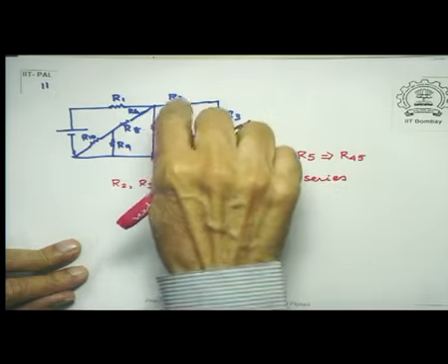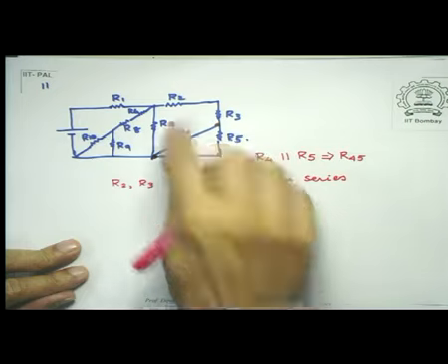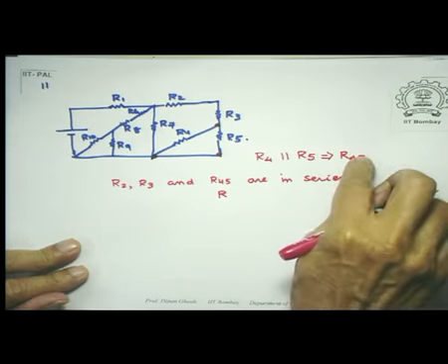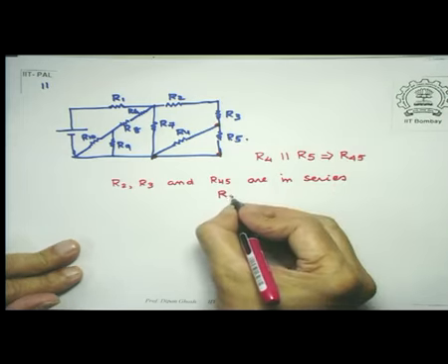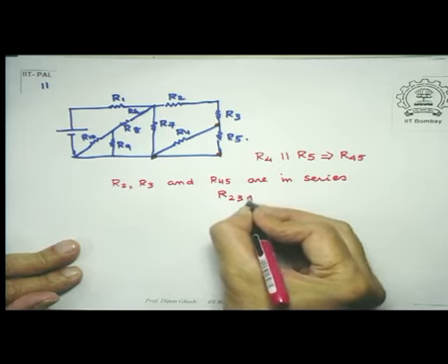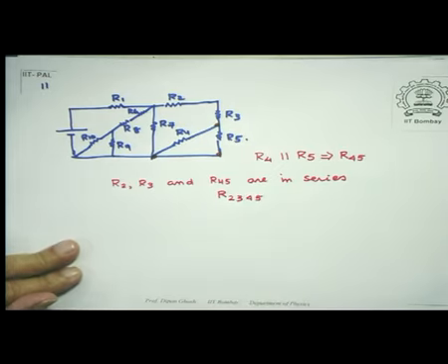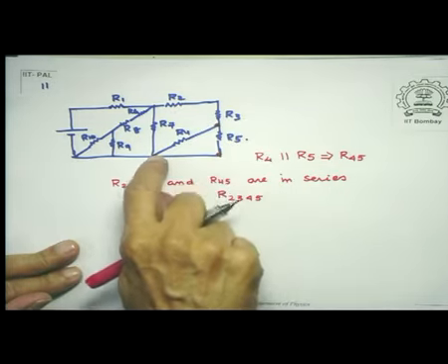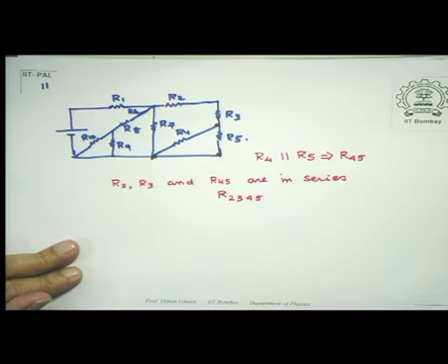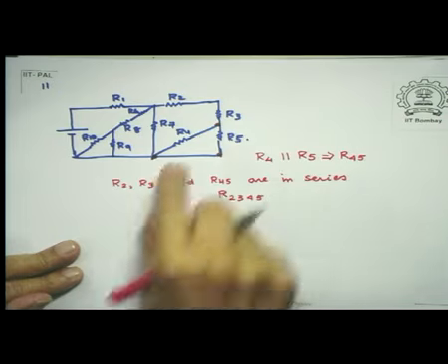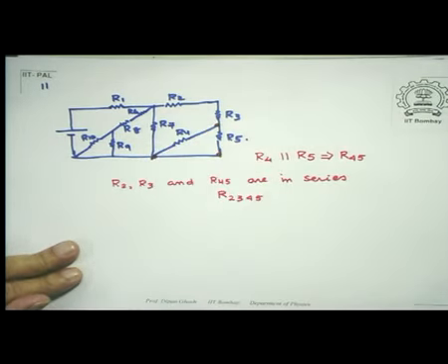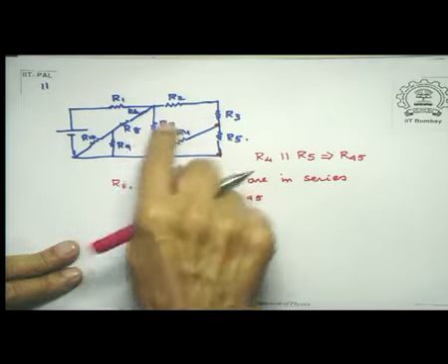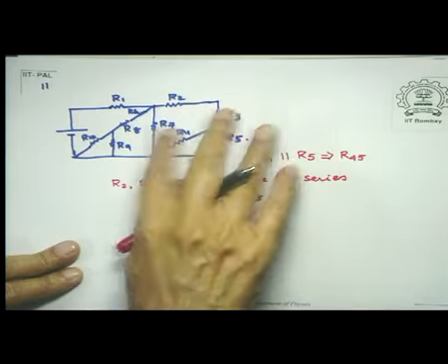So this section now, this and R45 here. So R equivalent will be, well, this was already 45 and I add 2, 3. So let's call this R2345. So this R2345 is obviously parallel with R7. So I write down that this is parallel there. Now, once we have done that, since the numbers are going on increasing, let's call that R7 prime.